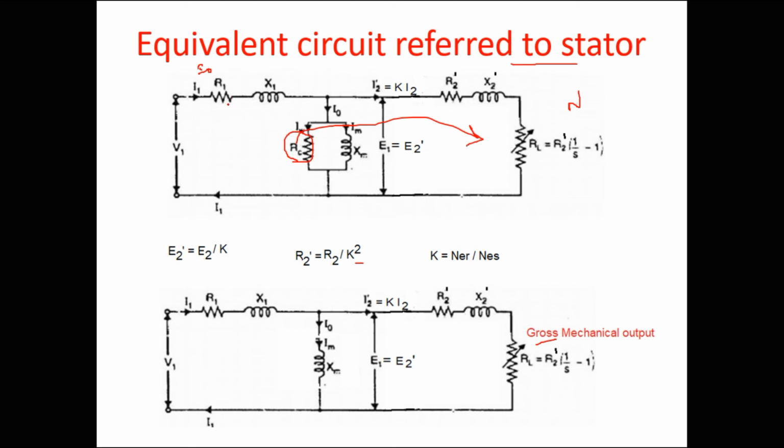It means this R1 and X1 is going to have an impedance drop. It is going to have its own loss, like copper loss and voltage loss, that is impedance loss and copper loss, and these two losses happen because of the flow of current through it. Simply we may call that current I1, but this I1 contains I0 too.